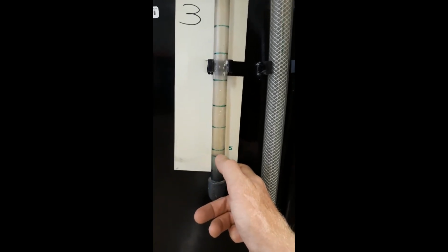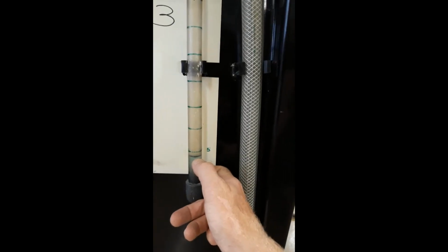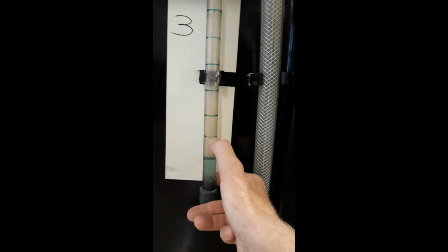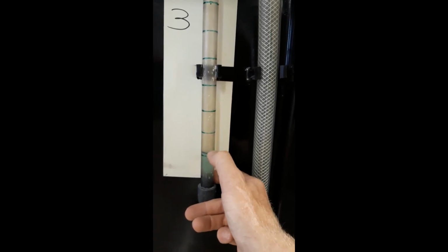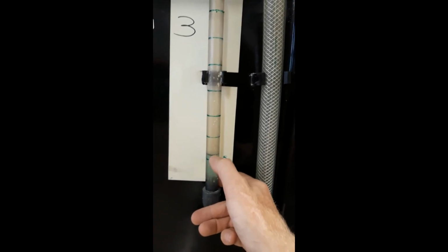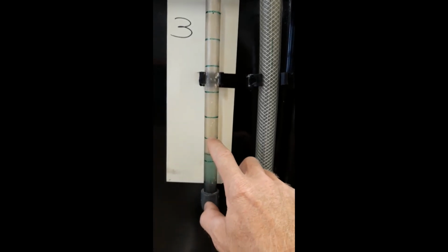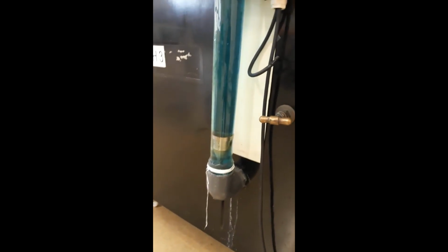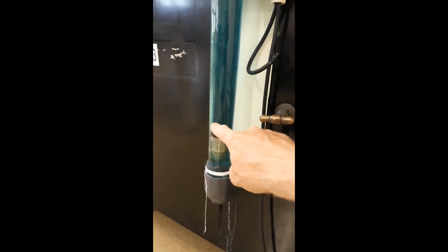So you can see the water is a little bit bouncy at the moment. So we wait for the water to settle. And if it reaches that line, I'm going to start my stopwatch. And when it reaches the next line, I'm going to stop my stopwatch. And that is a measurement of 5 liters of water. If the water is very bouncy, you might have to wait for the water to settle, and you will only be able to take a reading from this line. So it doesn't matter which increment you use, all the increments are in segments of 5 liters of water. So we will continue this procedure and jump in increments of 20 millimeters each time and take the flow measurements.